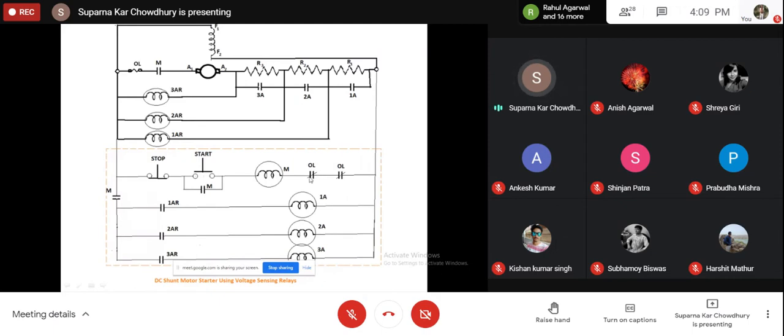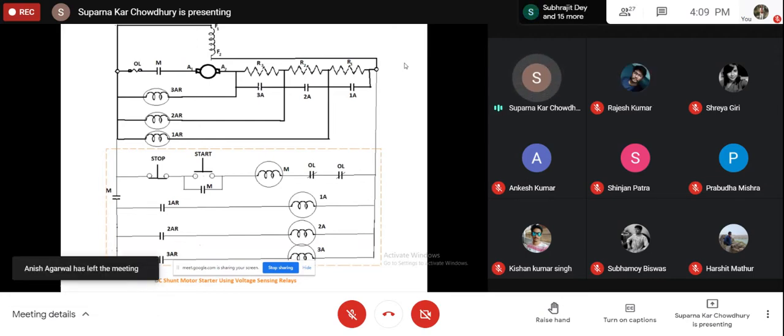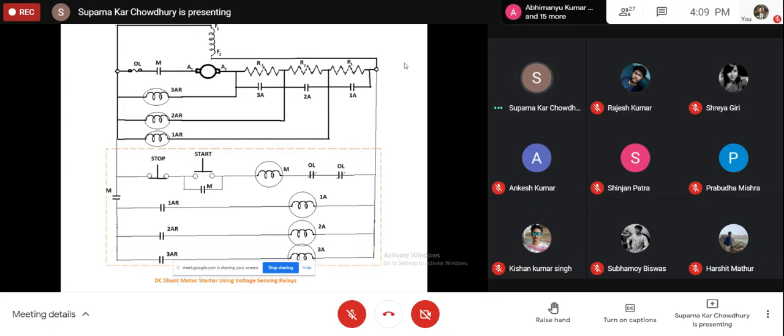This line shows that it is normally closed, and this one is normally open. Normally closed means when not excited, it is closed, and when it is activated, it will open. And normally open means when activated, it will close. So we will explain a few motor control circuits. The control or starting procedures you have already studied; only the representation of those in a semi-automatic starter setup.